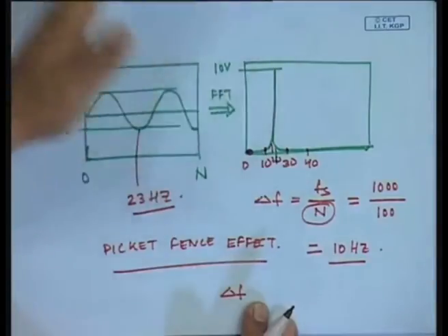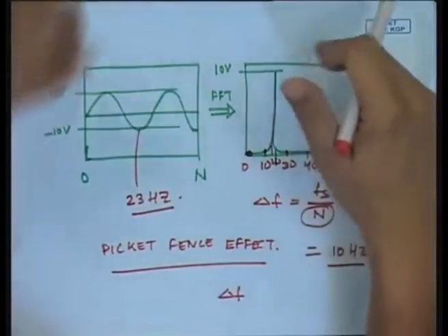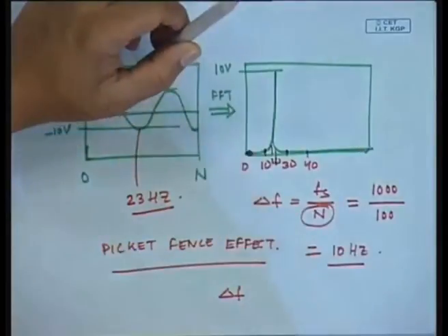If you do not see any frequency spikes coming up, you know you are not missing any signal, otherwise you are going to miss a signal. So, when you use an FFT analyzer, we have to be careful to play around with the signal, change the settings, see the number of blocks. How can I increase the block size? Of course, increasing the block size means more time, that is well and good, but then I should not be missing